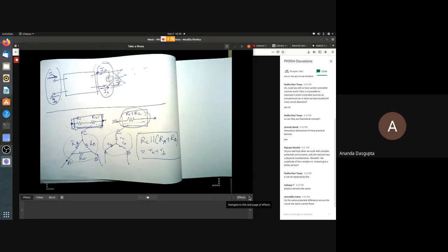Okay. So when I say why is the outside part important, something as simple as the R1 R2 series combination. There is a voltage division inside the series combination that no longer happens when you replace it by a single resistance, right? You don't have two resistances, so you don't get a potential drop across one resistance and another drop across the other resistance. So the voltages and currents inside the black box might very well change. What happens is things outside the black box will not change. That is exactly what this